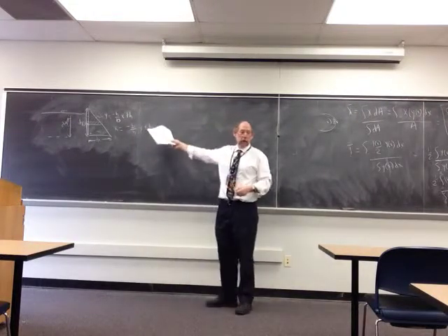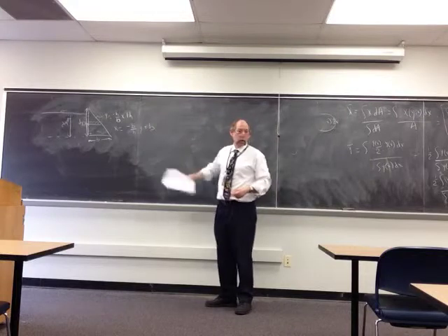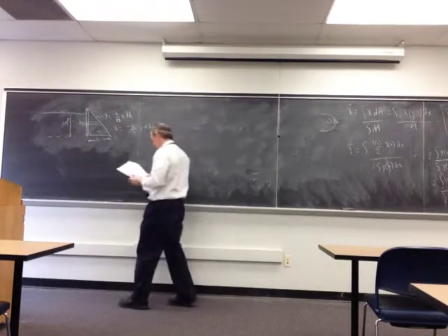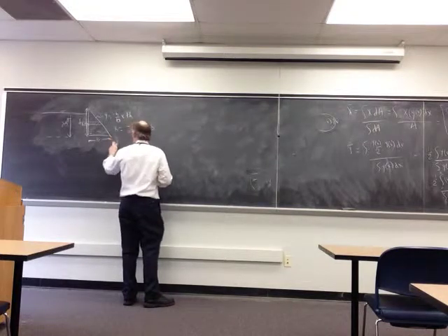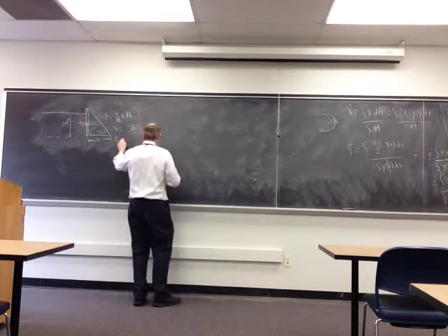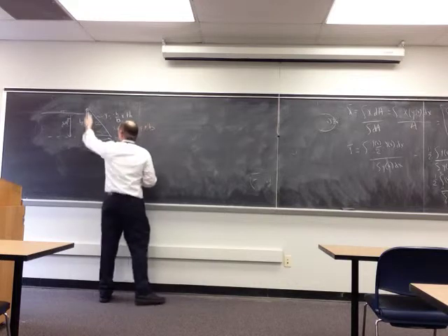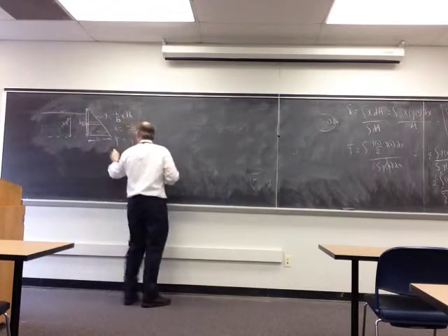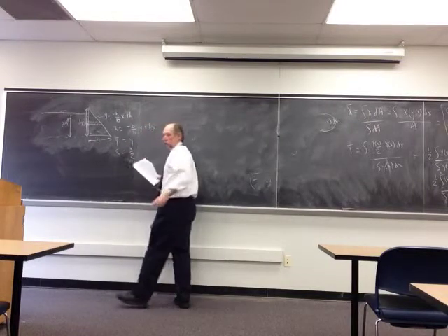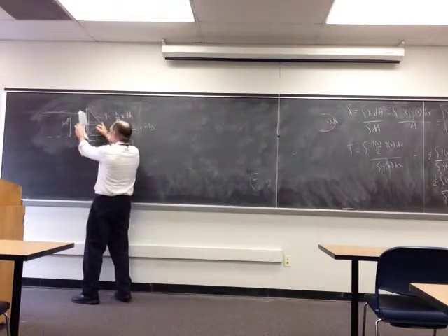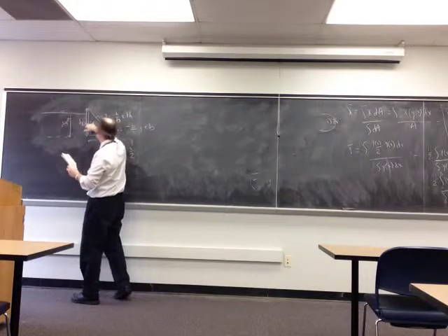And then we can integrate that equation with respect to y. And in this case, the y component of the centroid is equal to whatever y we have, and the x component of the centroid is equal to 1/2 of x, because now we're looking at, this is your length, and the centroid's going to be halfway.